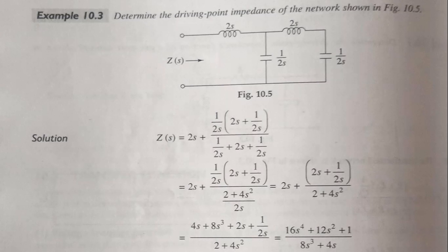So simply what we are doing is converting from the time domain to the frequency domain. We are converting the voltages, the currents and the impedances. We are looking for the series and parallel circuitry and trying to simplify with the help of Ohm's law, or the current and voltage division rule.